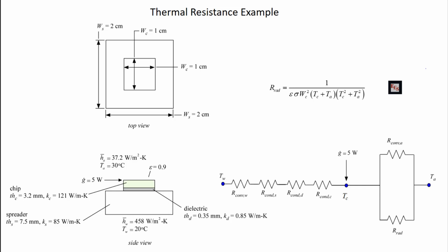And so at this point, there's kind of 2 choices that you have. Choice number 1 is you continue to add equations, hoping that eventually you'll get to a point when you hit solve, you have enough equations and enough unknowns. And that's not the best choice, I would say. The best choice at this point is to do what I would call a guess, and then eventually close up your guesses, right? So if I were to make a guess for what this chip temperature was, it doesn't have to be right or even very good. It would let me calculate this resistance, right? And if I can calculate this resistance, I can check that equation, and then I can continue going through the problem, always remembering that eventually I better be able to solve for that chip temperature that I initially guessed, right? And then I'll be done.